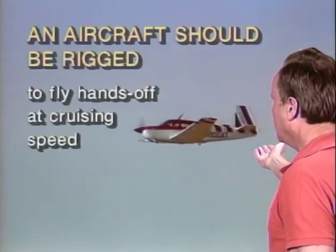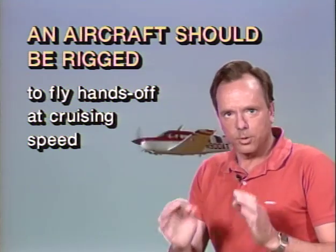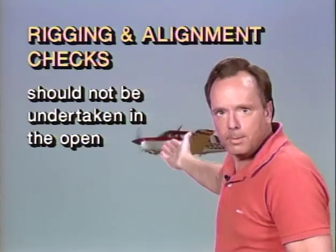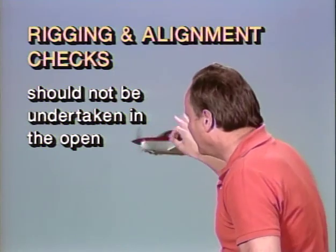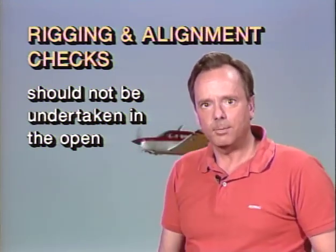Now let's talk about aircraft rigging and rigging checks. Now, an aircraft should be rigged to fly in a hands-off condition in cruise. So you want the airplane to be able to fly hands-off at cruising speed. Now, rigging and alignment checks should be undertaken in the open, and that would be by far the best thing to do. However, if this cannot be avoided, the aircraft should be positioned with the nose into the wind, so the wind is minimized as a factor in the rigging and alignment of the aircraft.